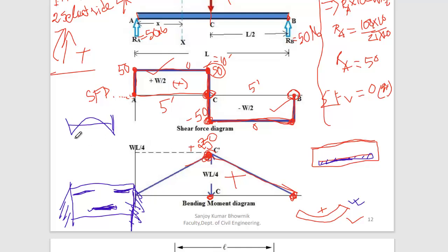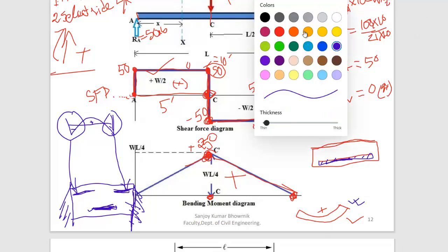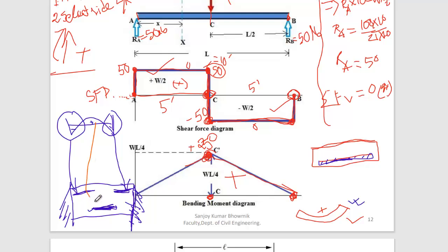Do you understand? So this is the negative moment, this is the negative moment, this is the positive moment. So that's why in a typical beam with fixed support on both sides, you'll find this kind of diagram, and the upper layer in this negative zone gets the rod for this. This negative moment will be resisted by this rod, and this positive moment will be resisted by this bottom layer rod.